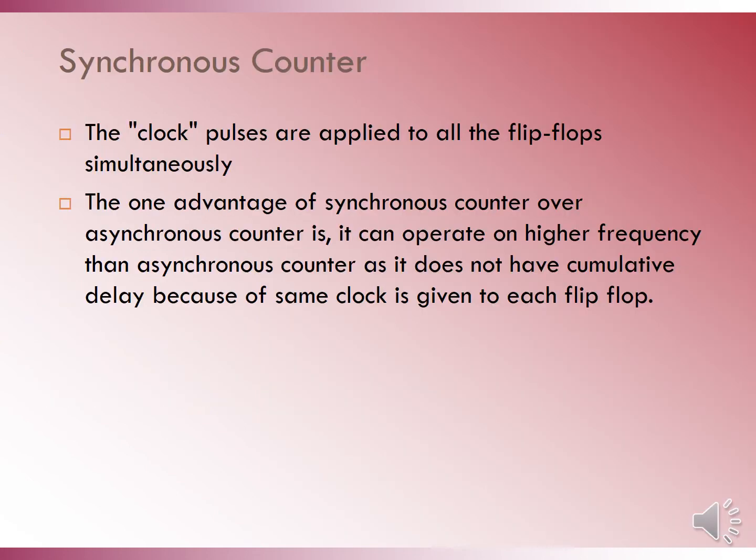Next we move to the design of synchronous counters. In synchronous counters, as we have seen in the previous slide, the clock pulses are applied to all the flip-flops simultaneously. So one advantage which we get in a synchronous counter as compared to an asynchronous counter is that it can operate at higher frequency. Why? Because the same clock is given to all the flip-flops.